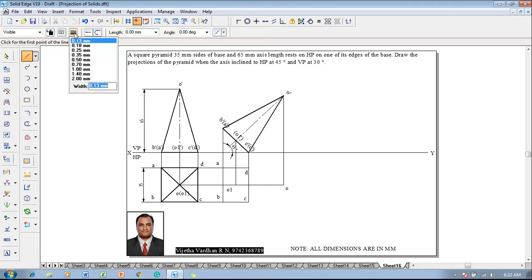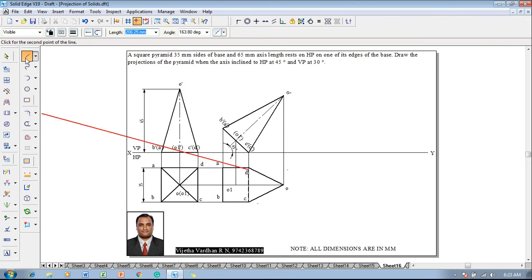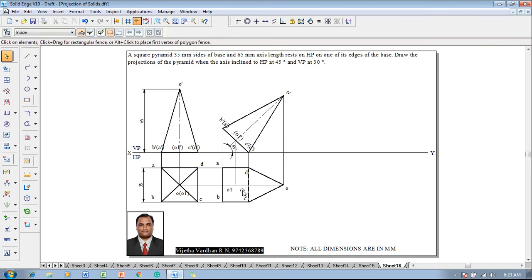Now according to the rules of visibility, first we should complete the boundary line. Now from the intersection A to B, B to C, C to O, O to D and D to A is going to be the boundary line. Now when the observer is seeing from the top, apex is nearer to the observer and base is away, henceforth the base edges must be invisible, that is CD is going to be the invisible edge. Now CD is not connected properly, so we'll repeat that one.